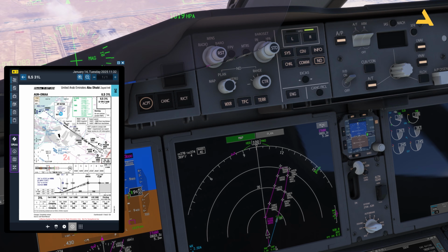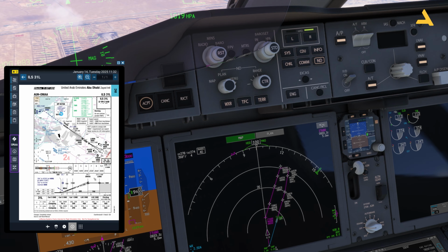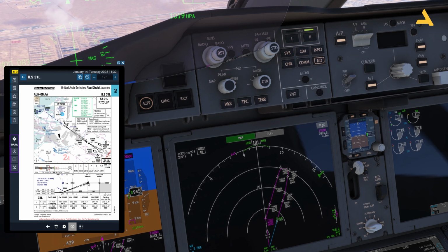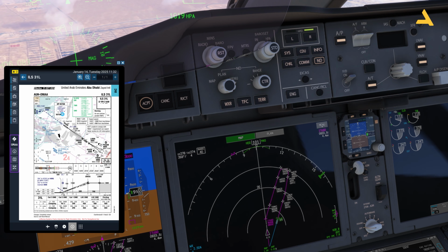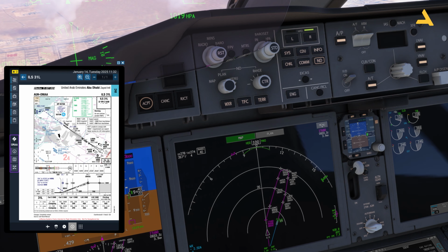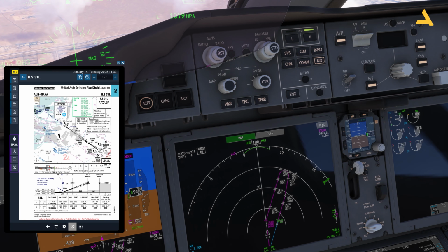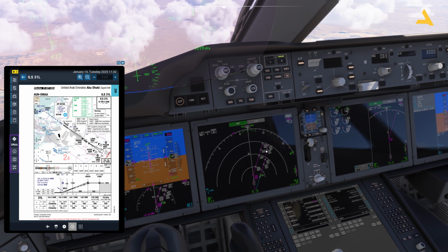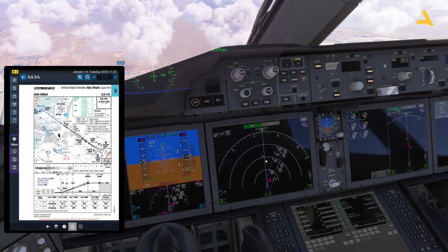D distance 13.2, and once the plane is at this point, 9.2 nautical miles before the runway, then the plane will start to follow this glide path, or rather glide slope, because if you're performing RNAV or RNP approach, it's glide path, and in ILS you call it the glide slope. But in these charts you have GP. So now I will just wait for the plane to reach this point Pegam, and then I will just take you from there.